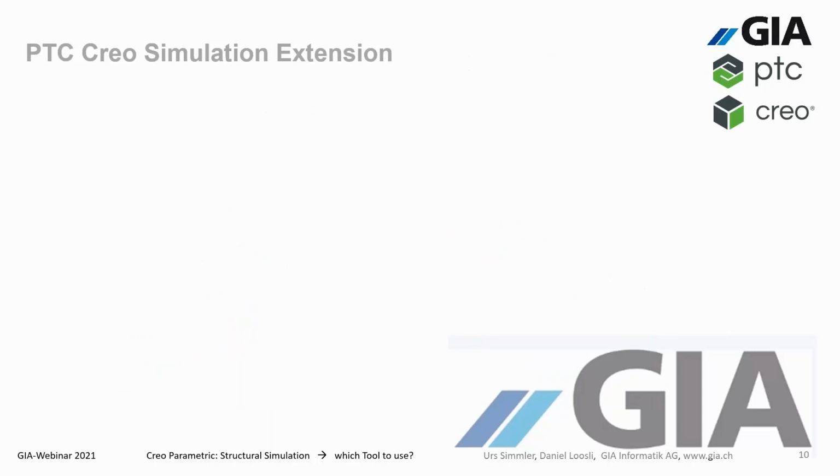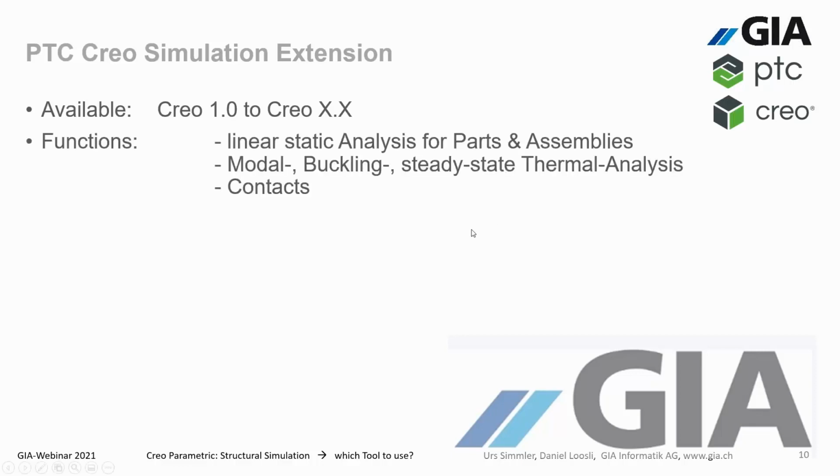Then the other tool we can use is called PTC Creo Simulation Extension. This is available until, I don't know. With that package, you can do linear static analysis for parts and assemblies, modal, buckling, and steady state thermal analysis.